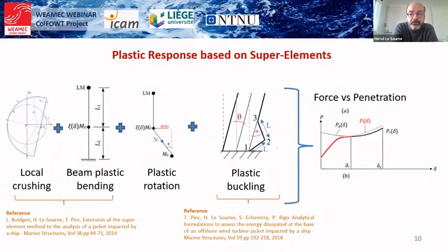For each deformation mode, analytical expressions have been derived or taken from previous research projects performed by ICAM and University of Liège. And combining the 4 deformation mechanisms, we can obtain from analytical expressions the evolution of the resistant force as a function of the penetration of the ship into the floating structure.